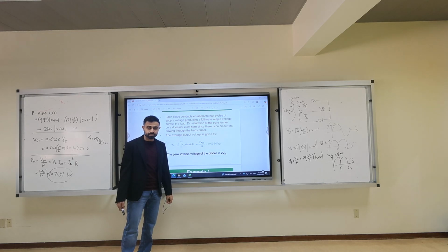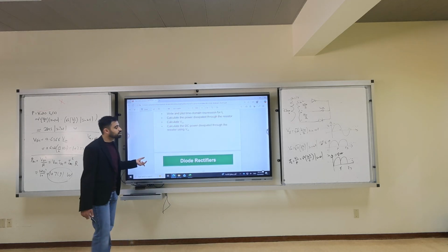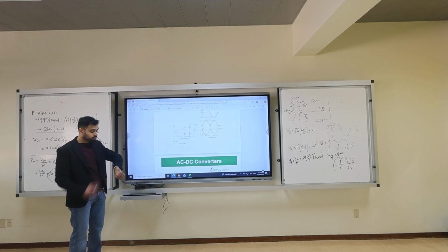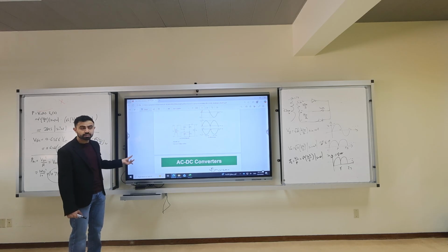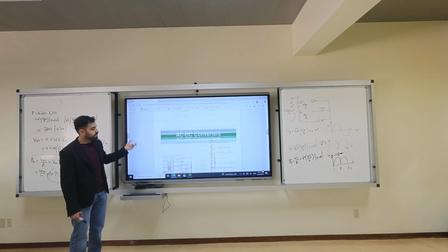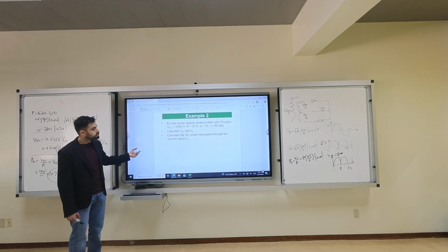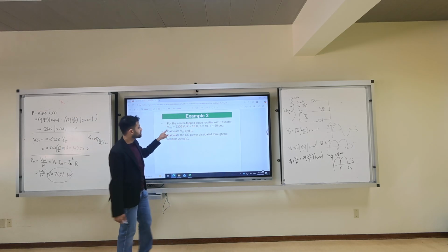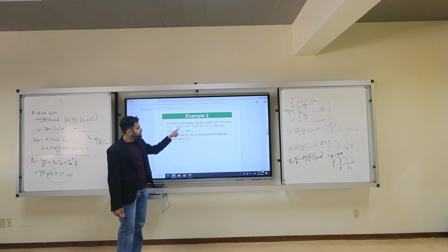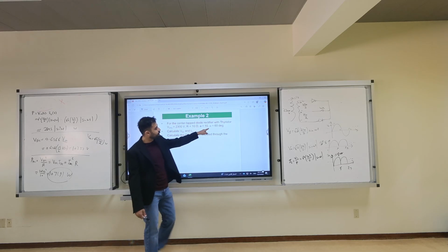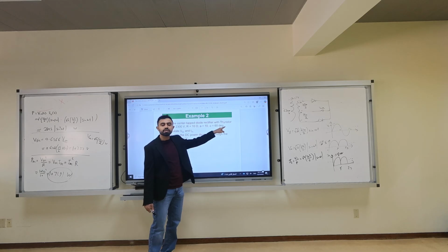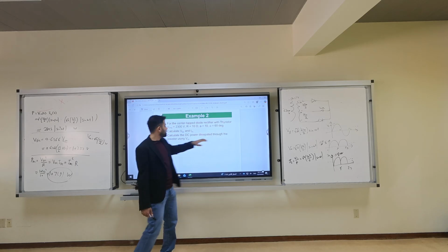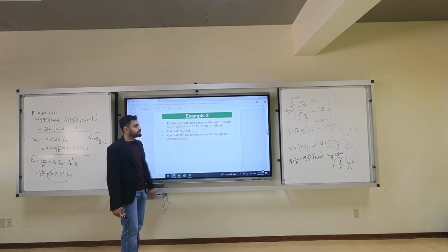Clear? Yeah. Now here is a more challenging question, and I'm rushing it because we have too much material. Okay? We're late in the curriculum, and I have to teach you these things. Otherwise, I'm not doing my job. For a center tap diode rectifier with thyristor, we have VRMS is this, R is this, a is 10, and we have a firing angle of 60 degrees. Calculate VDC and IDC.